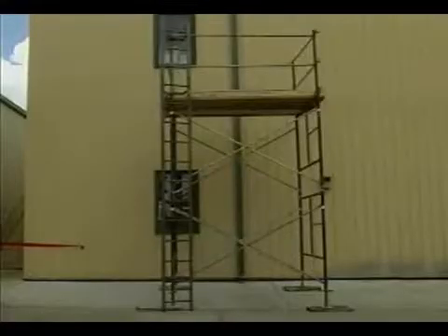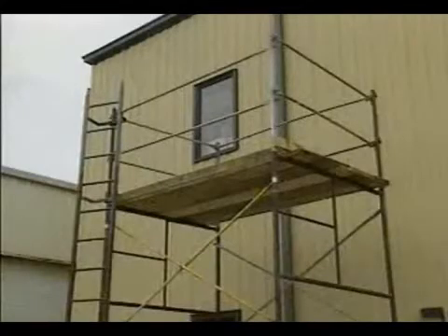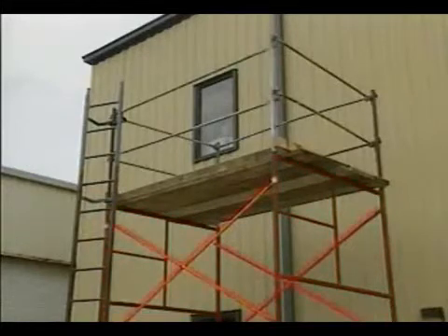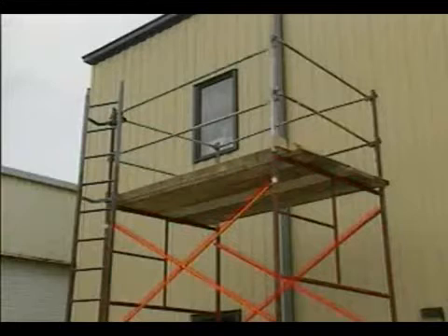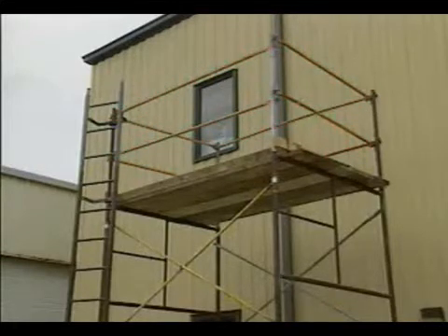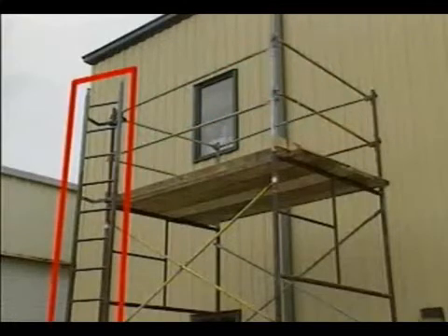A tubular welded frame scaffold, which is sometimes called a tubular buck scaffold, is one type of scaffold that can be used to support personnel and materials. Basically, a tubular welded frame scaffold consists of prefabricated vertical end frames, or bucks, and diagonal cross braces that fasten between the frames. Horizontal members are attached between the upper end frames to serve as guardrails. Access to the top of the scaffold is provided by a ladder that's built into the vertical end frames or attached to them.